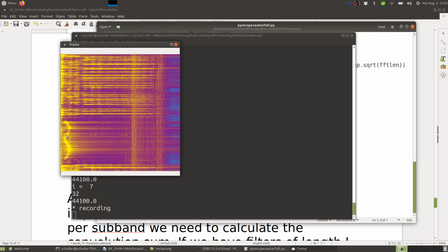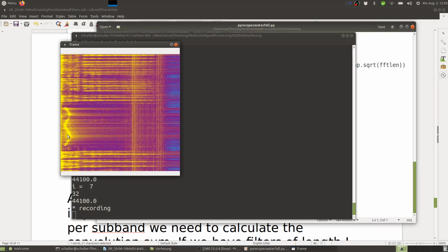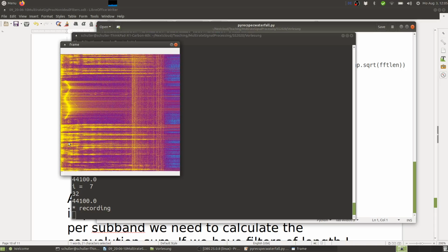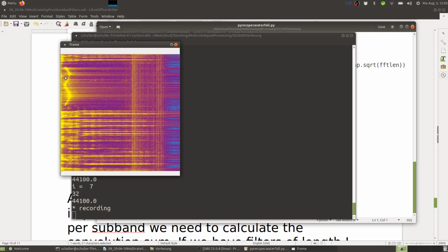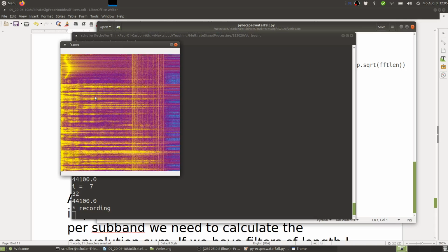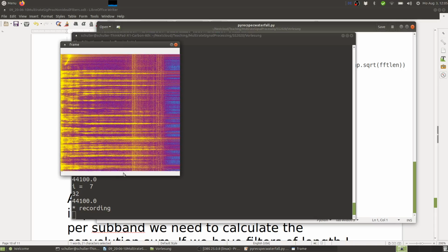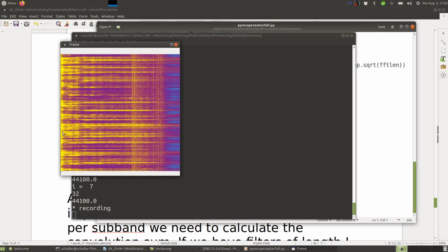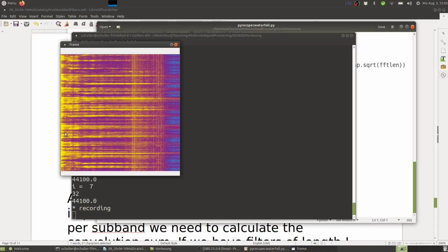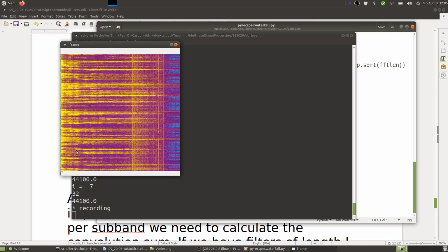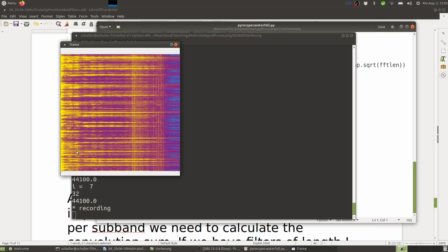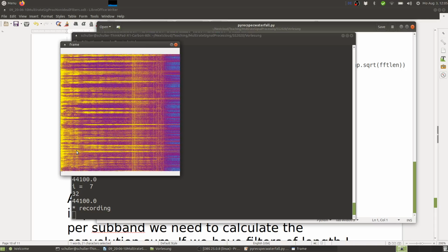So then this line tells you where my whistling frequency is. So here high pitch, then here low pitch. And you can see when you go up, it's earlier times. So this is a typical time frequency decomposition. So horizontally we have frequency, vertically we have downsampled time, right? So this is the block index. That's why vertically we have the downsampled time, in this case downsampled by a factor of 2048.